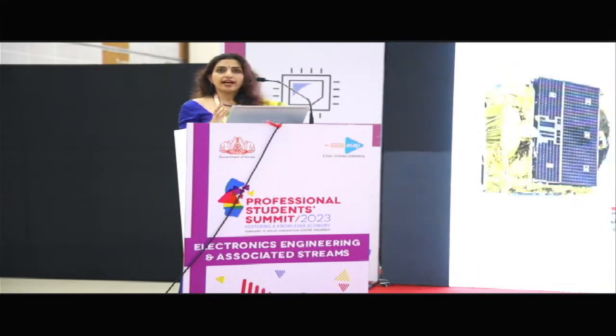This is what we have done in GSAT 9 in 2017. Here also, we flew with a Russian thruster, but all the electronics, everything, was ours. And here NSSK means north-south station keeping. It is required for a spacecraft when it is in orbit, and that was purely done with electric thrusters.